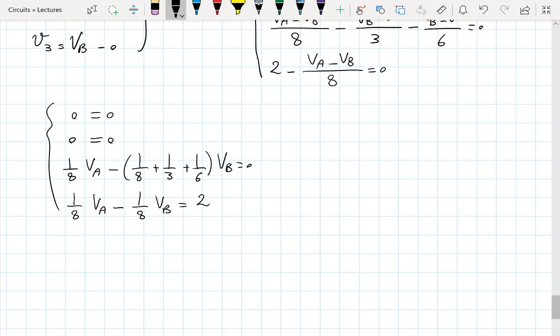Now, maybe I'll remind you of what I said in the first or second lecture when I briefly talked about these node voltages. You can probably find this in your notes. I said KVL is nothing but a manifestation or another representation of the fact that voltage is a well-defined quantity, that you can say each node has a well-defined voltage. If you do that, indeed, if you write the element voltages in terms of node voltages, KVL will have automatically been implied.